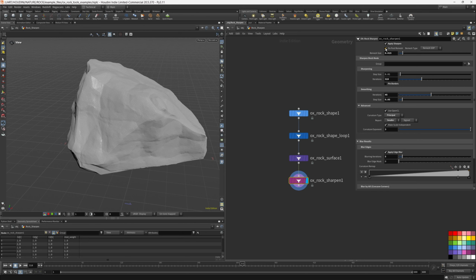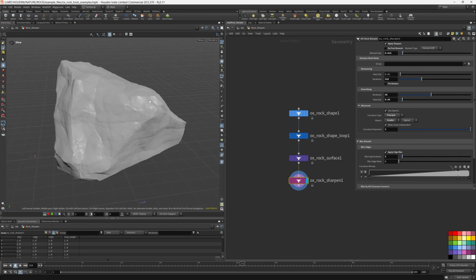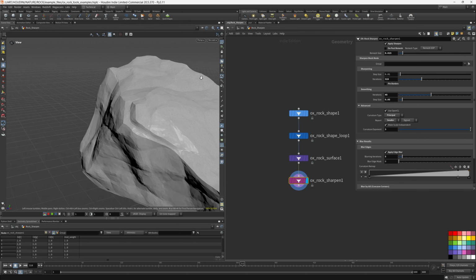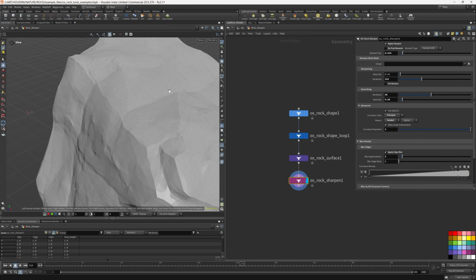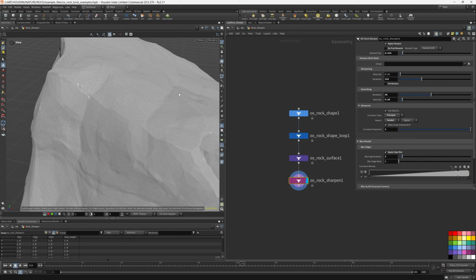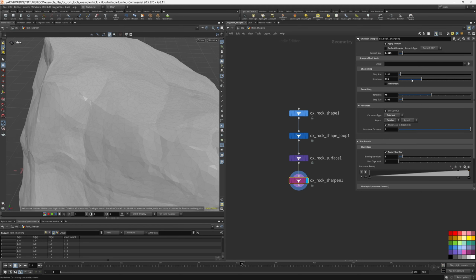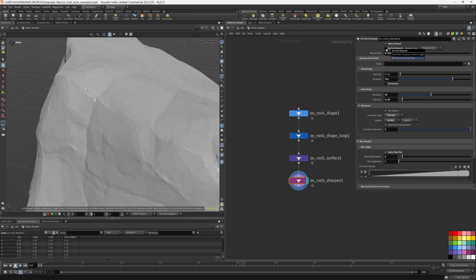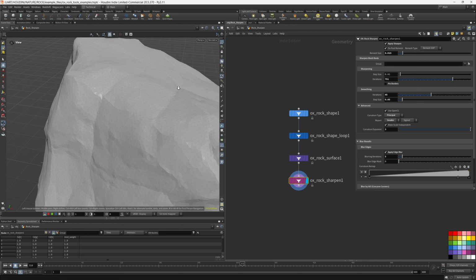And I've noticed that after you use the sharpen node, you're most likely going to want to remesh because it really gives you not a bad topology, but just a warped topology. Really gets pinched, like the size of the polygons. So we have this post remesh here.